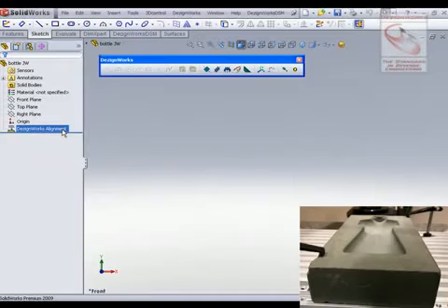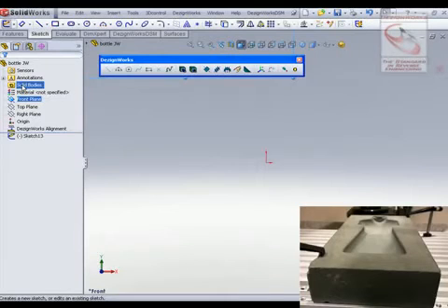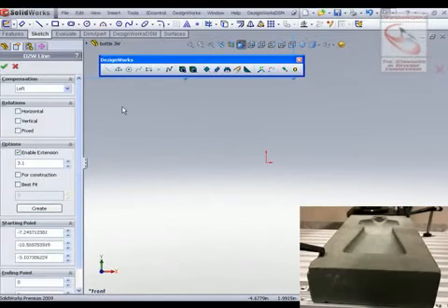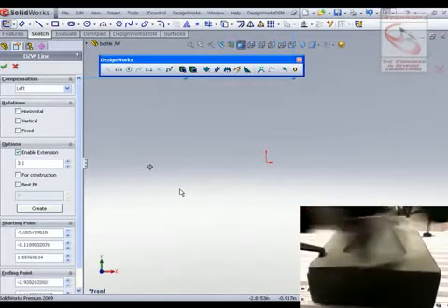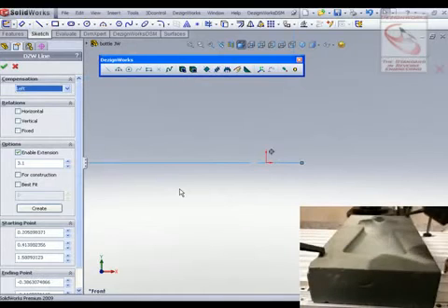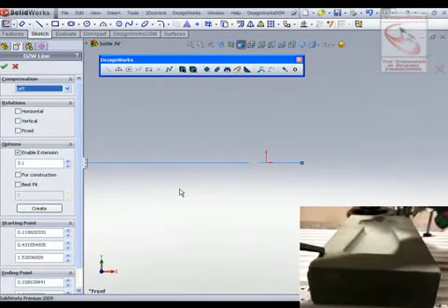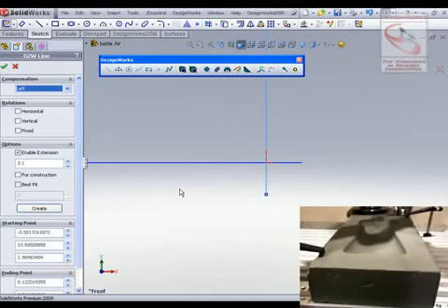In this demonstration, we're going to show you how we can do freeform surfaces. So we're going to pick the front plane in SolidWorks and start a new sketch. Now we can utilize all the SolidWorks tools and DezignWorks tools together. I'm first simply going to outline the part, and notice that DezignWorks runs right inside the property page. Also notice a nice tool is this Enable Extensions. When I'm digitizing, it actually extends the data, so I don't have to use the corner trim. I can actually use power trim and simply drag the ends together,